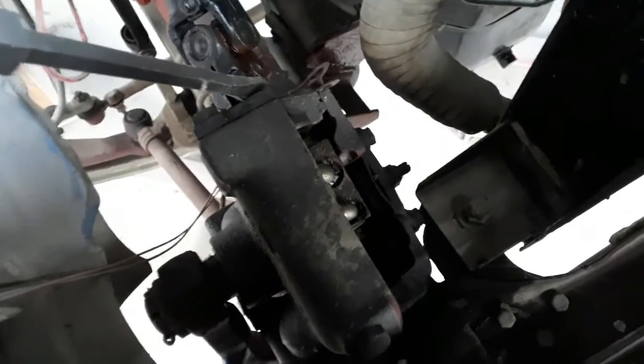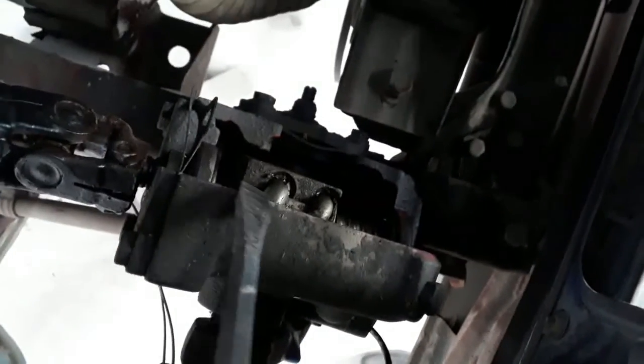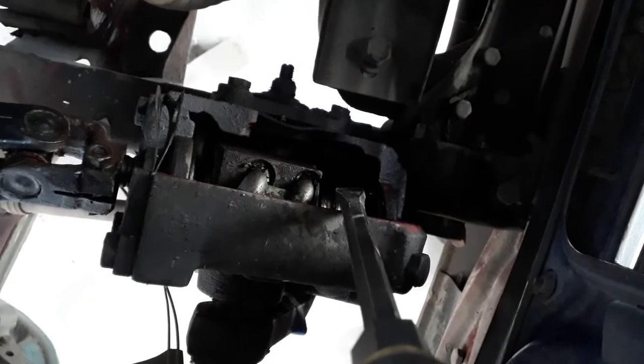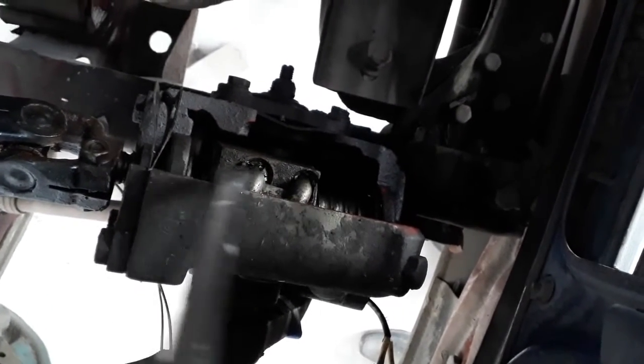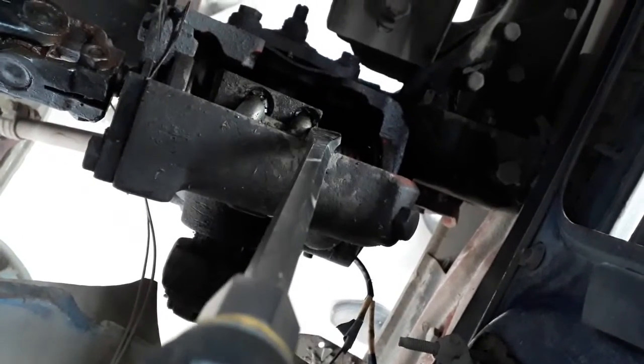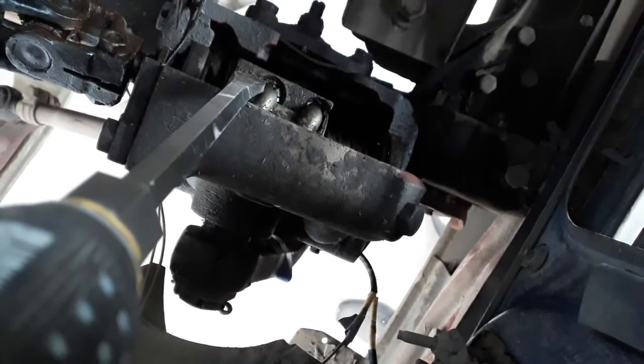This is the pinion, worm shaft and worm wheel. And if you see, this is the cut section of the recirculating ball type steering system. If you look closely, this is the worm wheel and the worm shaft. This shaft is the worm shaft, and this one is the nut. One nut is mounted on the worm shaft. Inside the nut there are some balls, placed in the channel of the worm.